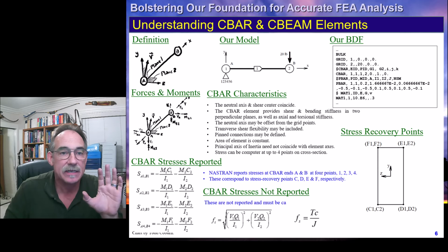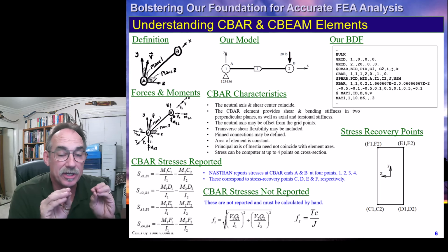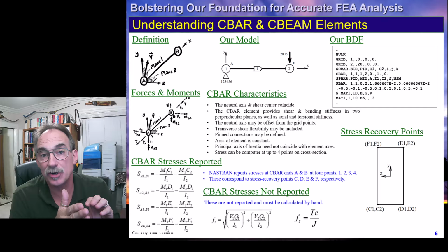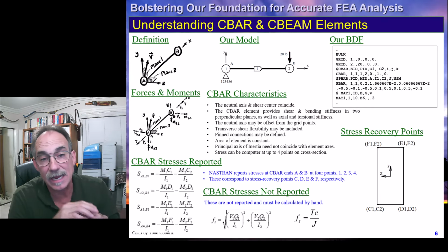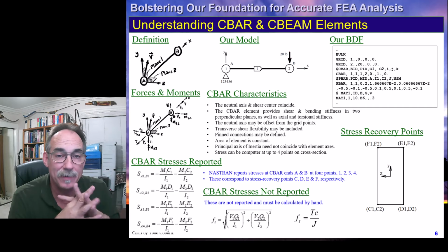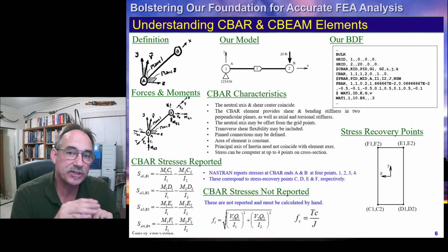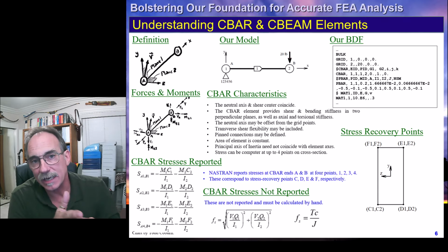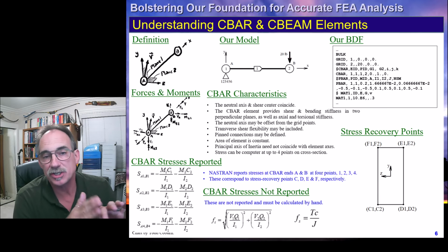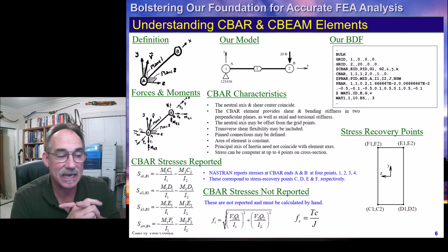C-bars and C-beams are another one of the more simple elements to use, but I've seen countless models where folks don't understand the moments of inertia and how those resist bending. The way they're aligned is not necessarily intuitive, not the way all of us would think it should be. And so we find people that have flipped normals, bars where one bar is connected to another bar and the one moment of inertia switches to another plane and back again, and panels that have the same problem.